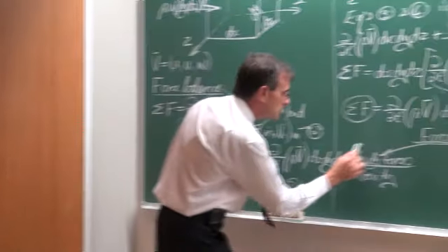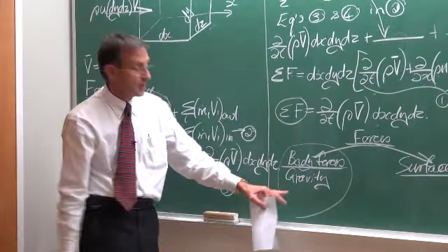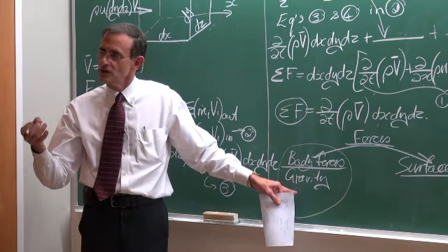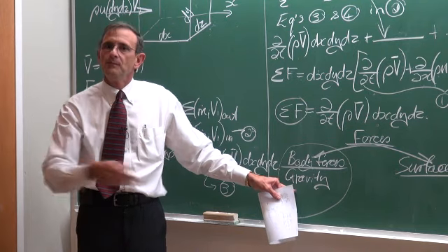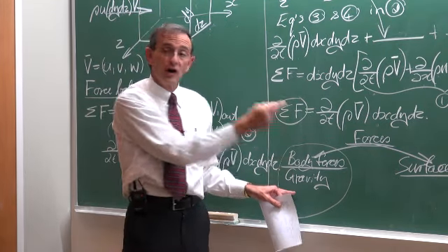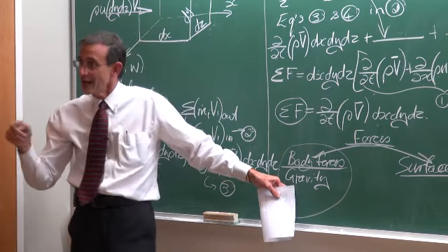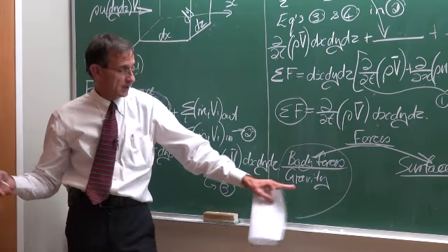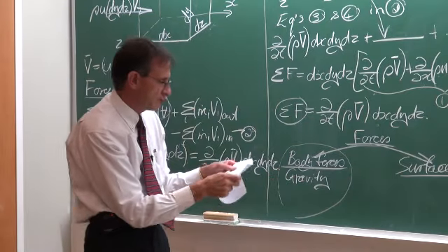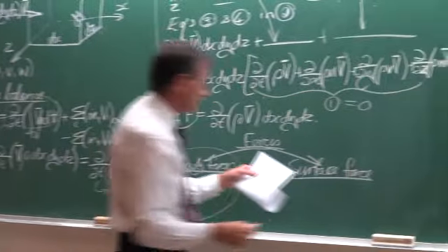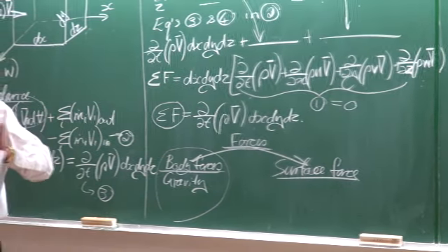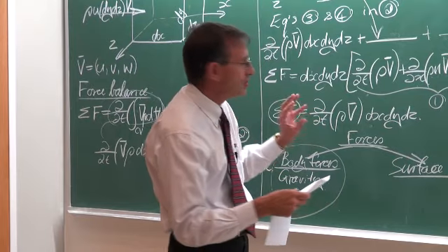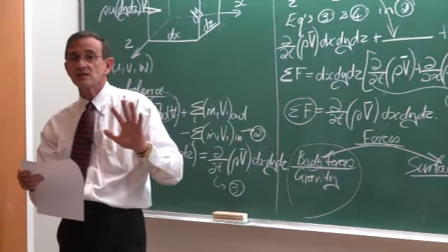You need to know that there are forces like that, because if you use a CFD package, a computational fluid mechanics package, you have to go back to the equations and correct it if necessary, or take it into consideration. Surface forces has to do with stresses on the sides of the control volume, and there are different types: hydrostatic ones and viscous ones.